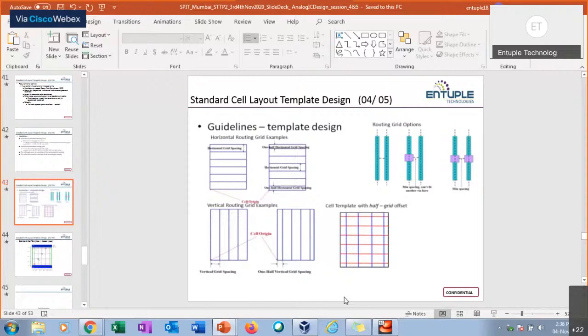Then we went on to the physical verification process. We started with DRC, LVS, and finally we went for parasitic extraction. Then we imported those parasitic components into the schematic in order to check their impact. Once that was done, we ran the simulation and checked the results. By comparing the pre-layout and post-layout propagation delays, you will have an idea of the impact of parasitic components on your schematic. Finally we generate the GDS file.